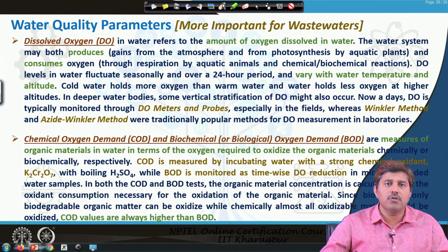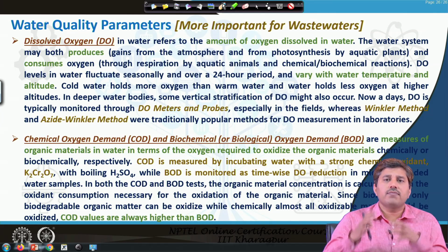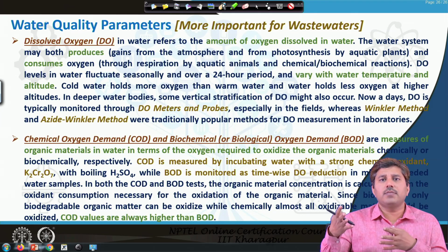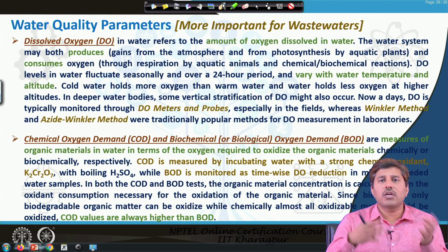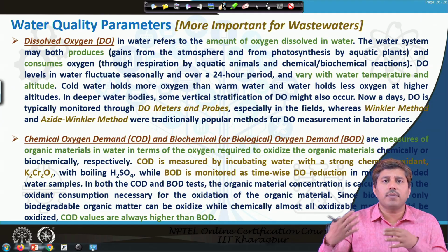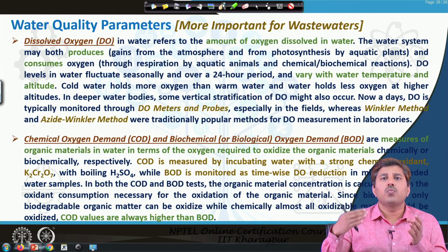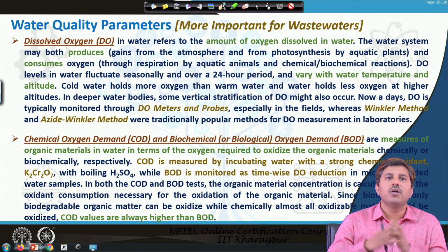or all the oxidizable matter present in the water which can be chemically oxidized. So, that is why COD values are typically higher than BOD values, because whatever is microbially oxidizable can also be chemically oxidized. So, the BOD component is already there in COD. In addition, non-biodegradable compounds which cannot be oxidized biologically but can be oxidized using dichromate are also included in the COD. So, we usually get higher COD values than BOD.